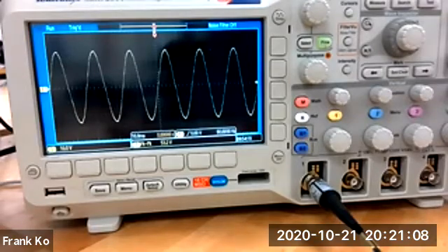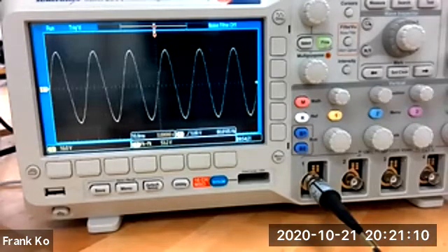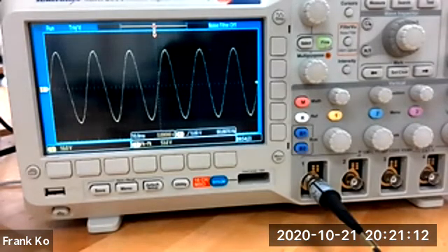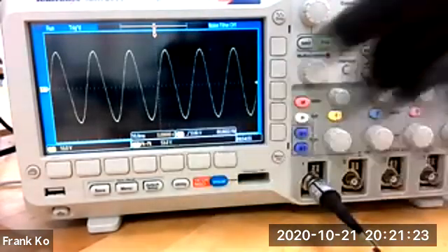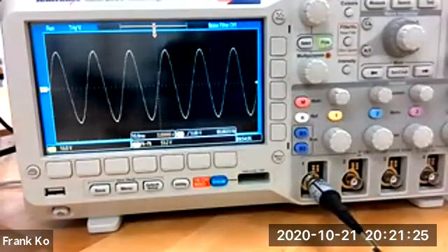All right, my friends, now that you've been able to confirm your waveforms, and your waveforms are slightly different than mine in terms of amplitude. I have a slightly different transformer. Mine's hovering above 50 volts peak to peak. Yours is about 38 volts peak to peak. That's fine. At least all of yours are consistent. What we're going to do is build a half-wave rectifier.